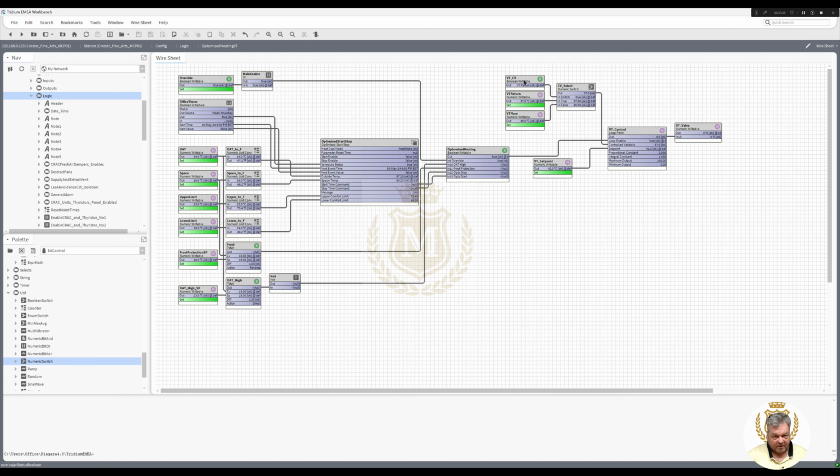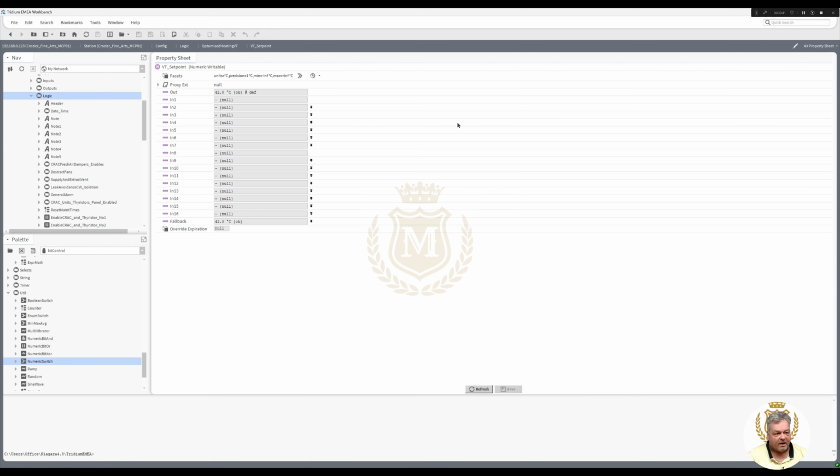So they've got the option of using flow and return. They've got the option of adjusting the set point. I think what we would need to do with that is give them some limits. So you probably don't want to go above 50, and you don't want to go below 20. Well, I'll tell you what, let's just put that to 80.